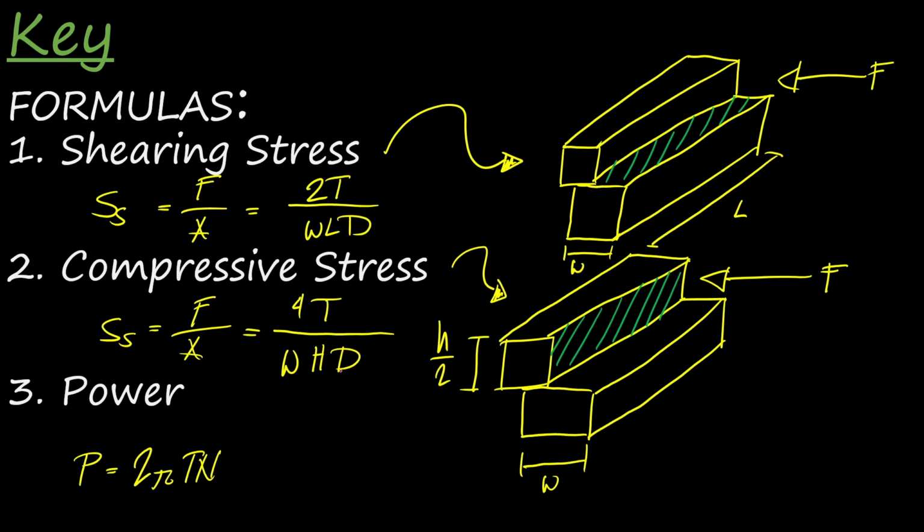Hello everyone, today I'm going to discuss keys. So we have formulas regarding keys. We have shearing stress. Shearing stress is just force over area. So we have 2T over width times length times the diameter of the shaft itself.